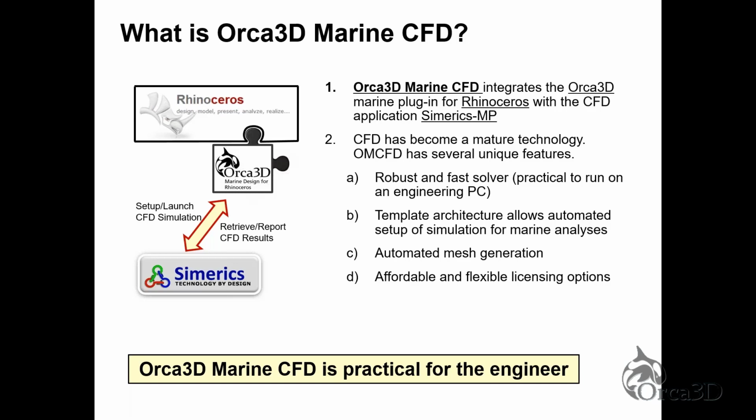Later on, you might even find that you need more RAM than 16, maybe 32 gigabytes, which is what I have on my laptop. But the other thing to keep in mind is the faster your processor, the more cores you have. CPUs these days have multiple cores, and because CFD can be a heavily parallelized program, meaning it can be distributed among multiple cores, that means that if you have more cores on your computer, the CFD program can take advantage of that and run faster.